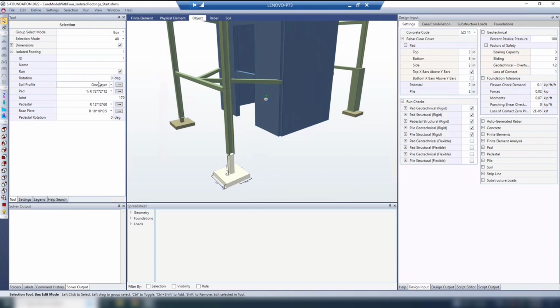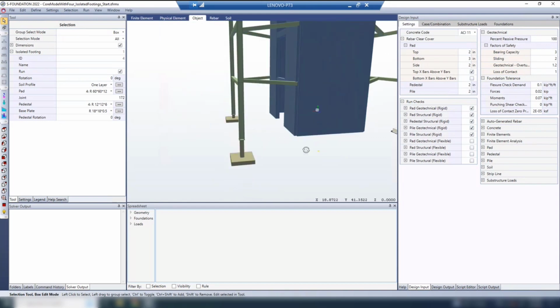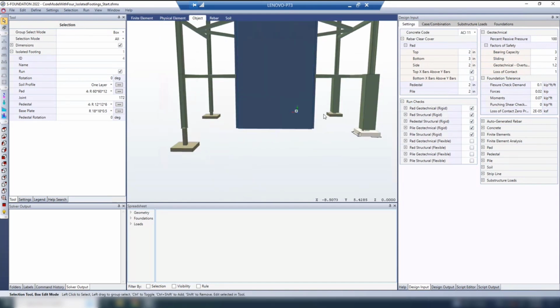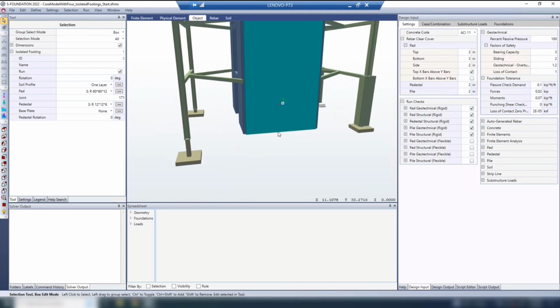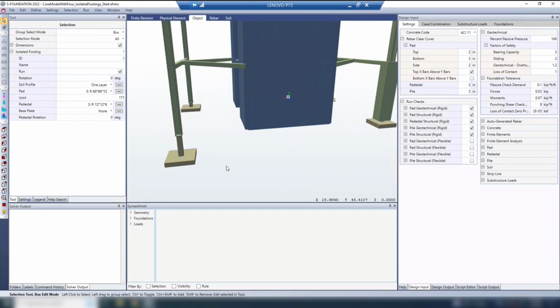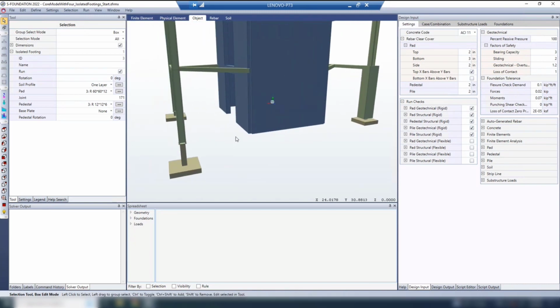This is footing number 1, and that's footing number 2, and then number 3 and number 4 is on the back side here. And the reason I did that is so the program knows that I'd like to look at all 4 of these individually and say, give me the size that's needed, even though some of the loads may be similar.